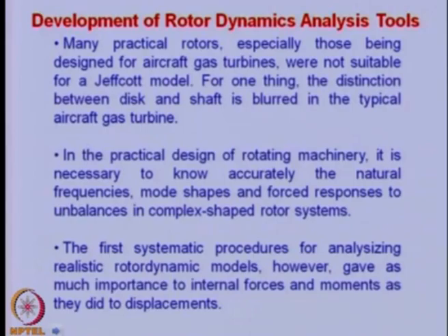Many practical rotors, especially those being designed for aircraft gas turbines, were not suitable for a Jeffcott model. For one thing, the distinction between disk and shaft is blurred in a typical aircraft gas turbine. In the practical design of rotating machinery, it is necessary to know accurately the natural frequencies, mode shapes and force responses to unbalance in a complex shape rotor system.